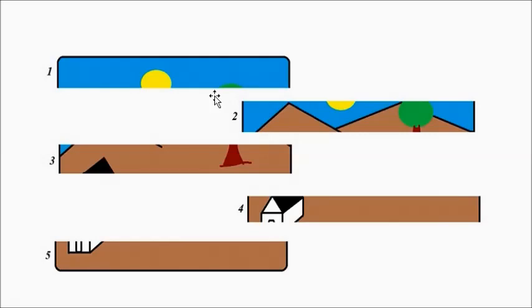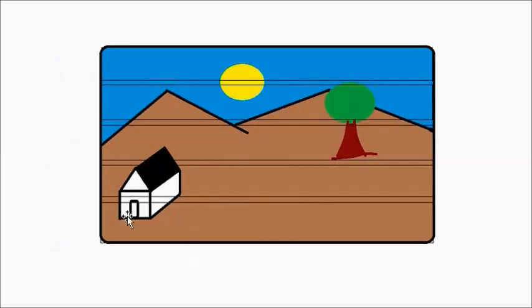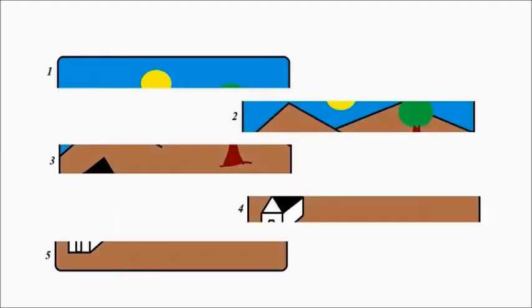Half is done at a time. Here the number of odd scanning lines is exactly equal to the number of even scanning lines. Just because of this portion, one extra scanning line, 5, is obtained, but actually the odd and even scanning lines are the same in number. It means there should be another scanning line here, 6, because they are exactly equal, half and half.